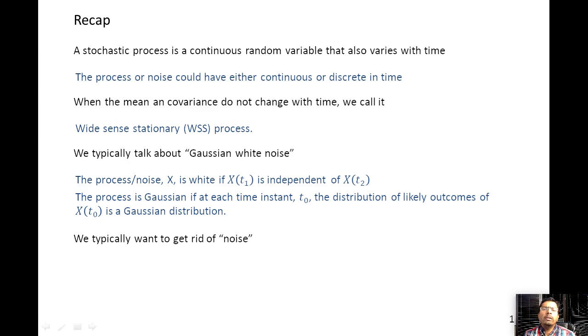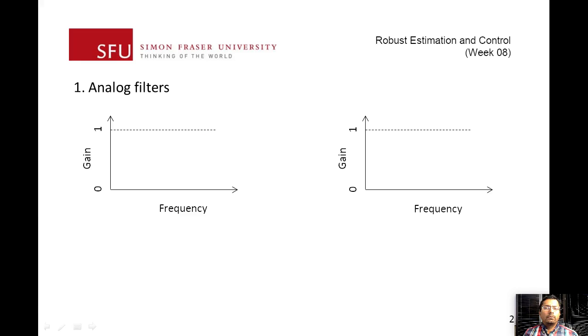The first approach we are going to be looking at, at least today, is doing a frequency cutoff, or frequency-based filtering, of our noise. So we will now look at some of the basic types of filters that we would typically use. You're going to have these laid out here, and we describe these as analog filters. The same concept actually applies in discrete time or digital filters as well, but it's just easier to draw in this particular case.